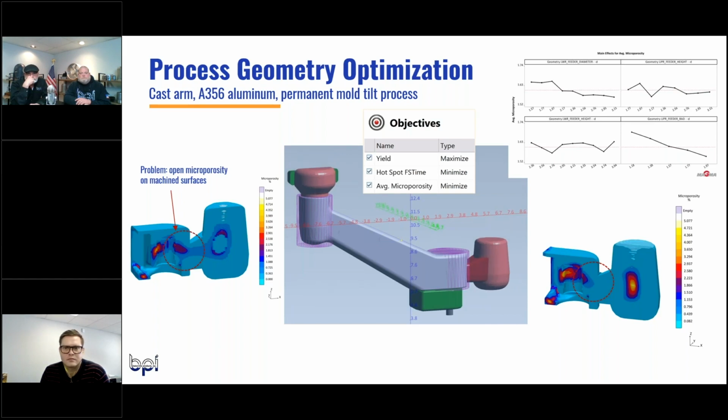the part is surrounded by a mold, whether it's sand or permanent mold. We're not filling the part. We're not bringing the metal in as we would to a gating system, but we're allowing, like you said correctly, we're allowing it to solidify from fully liquid state to solid and cool down to ambient if we have to.